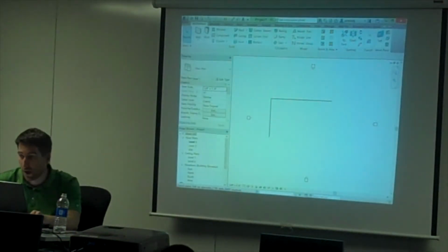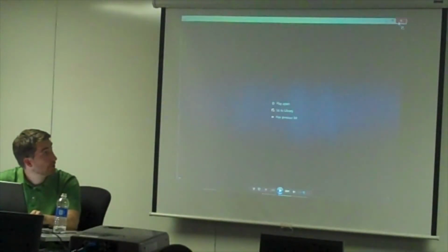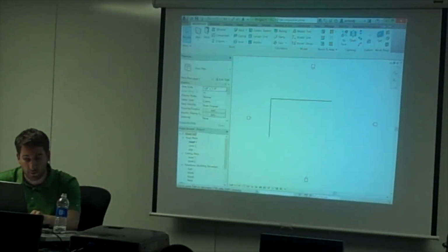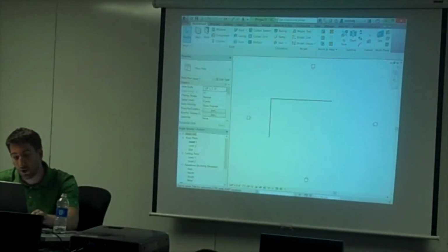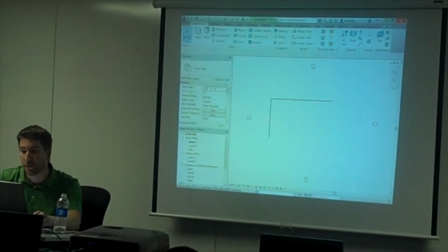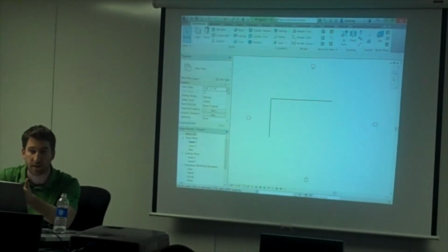While I'm in Revit, I might as well talk just a little bit about point layout. So one of the technologies that Autodesk bought recently is called Autodesk Point Layout. And what it's really intended to do is to bring the field and the model together through the use of a robotic total station. You see a lot of interaction between getting data in and out of the field on the infrastructure side. On the civil side, we've been doing it for a long time with total stations and GPS and things like that to lay out the ground, but it doesn't tend to be used as much in the layout of the building or the as-builting of the building.